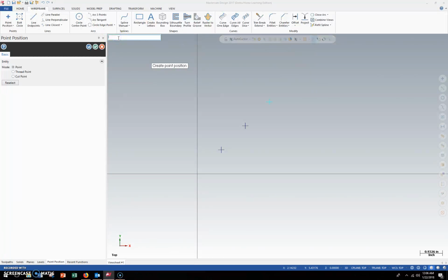It does take a little getting used to. You got to have a good handle on the X and the Y and the Z and where the Cartesian coordinate is too, because you can also do this in the other direction. If we go -1 comma -1 comma and then 0. Oops. There it goes. You'll see we're going in a different direction now. So instead of going positive, we're going negative. Do the same thing. -2, -2, 0. There we go again.